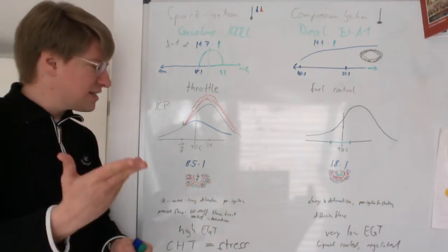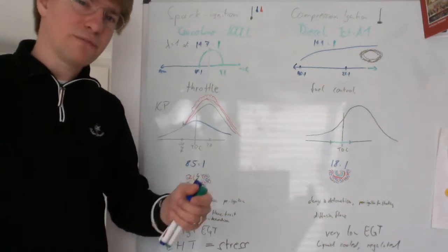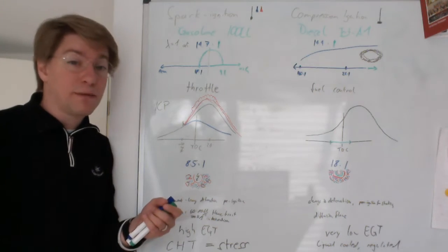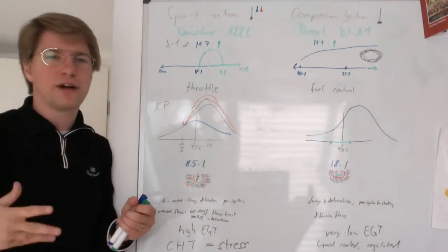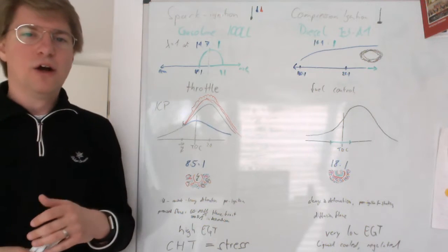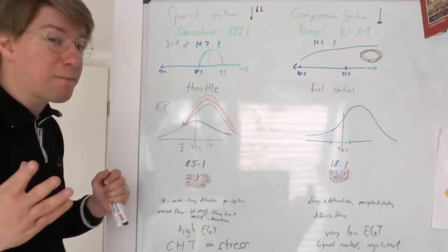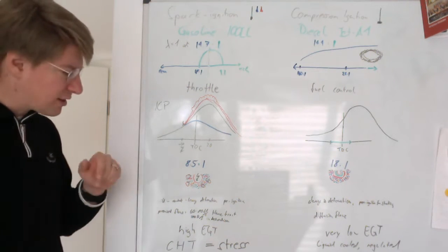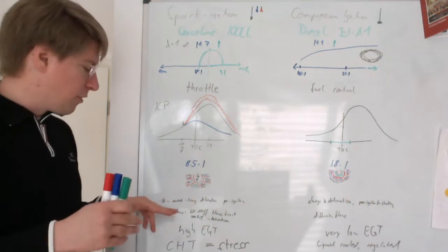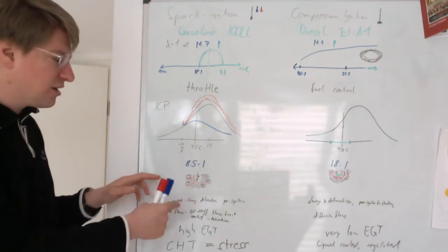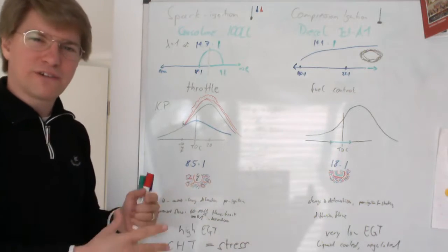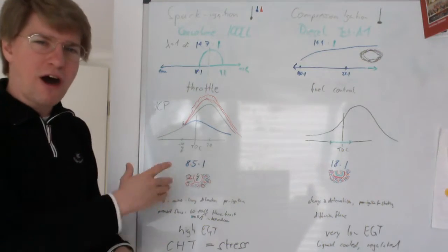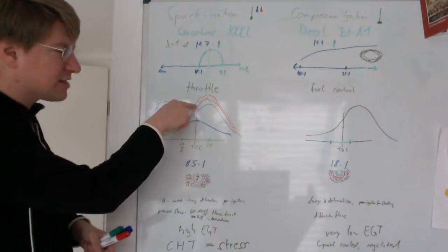And then, of course, as things get worse, either by jacking up the manifold pressure, if you have a turbo-normalized engine that is not set up properly, that allows the upper deck pressure and by extension the manifold pressure to get too high, or if you have a supercharged engine, you're not operating it correctly, in combination with this destructive, I call it, mixture, you can progress into moderate or heavy detonation, where instead of the orderly flame front, you have those pockets of mixture just going off at random in the cylinder, and this is what yields